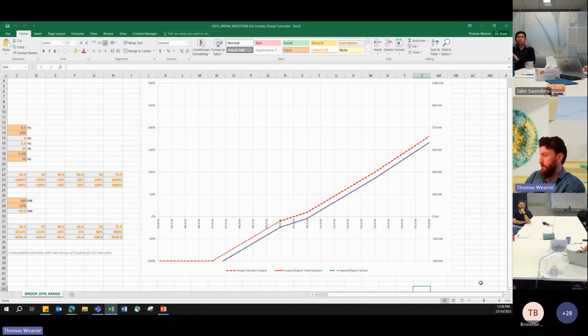Well, the trigger is the frequency that the site sees. So obviously any solar control or solar export control system is going to have a point of reference. It's going to have a meter. In this case, for Temple Bar, we've got a very high quality meter. And the advice from ComAp, who are on the line, is that we would probably be able to detect this as quickly as 500 milliseconds. We don't have, certainly in Web Supervisor or in our meter or anything else, the ability to confirm that. And this should really be tested with a high-speed logger in a controlled environment, like the testing we did at the CDU testing facility, which is for exactly this type of thing, where we can induce a contingency and observe the effect in millisecond resolution.